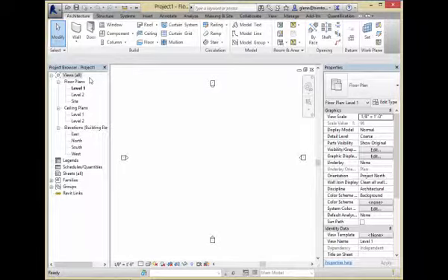Then for the finishes, just inside the boundaries of the rooms, I'd put a finished floor on top of the subfloor. So it's actually a floor on top of a floor. Okay, so that it's just the carpet or it's just the tile. I separate them out a little bit. So if I'm being really accurate, I do it that way. I'd model floors in two different layers. A subfloor that's continuous, a finished floor that's just room by room.